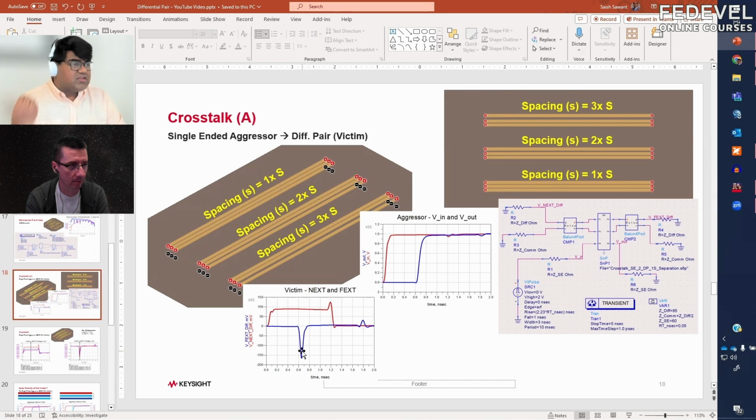Whereas for the near end crosstalk, the signal goes all the way and then comes back, so it usually has a round trip time. Its length is usually twice. You will see that it's positive and it's 1.2 nanoseconds long. So you also see the same feature, or the same signature, of the crosstalk. This is what we see out here.